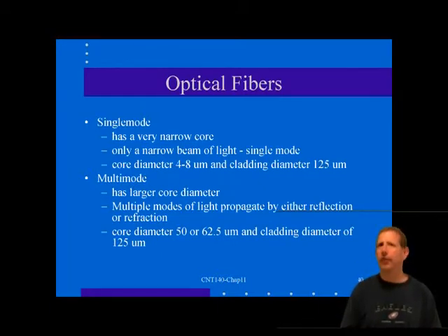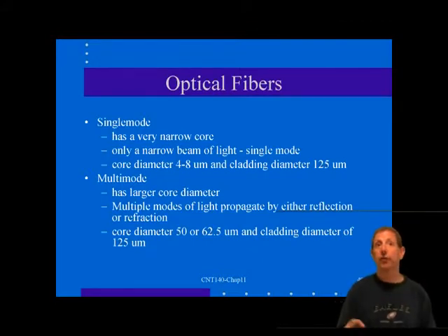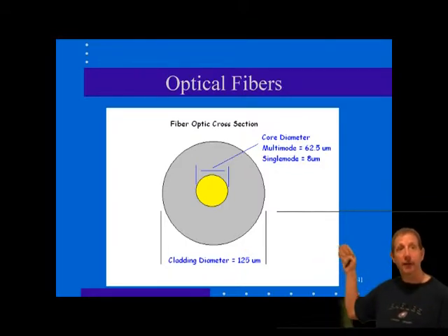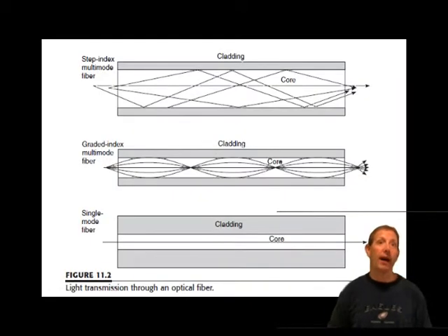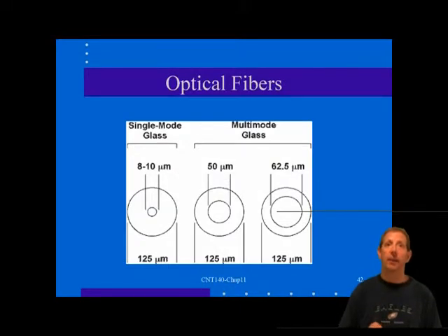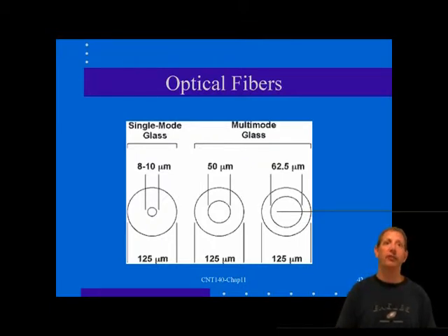Multi-mode fiber is further subdivided into two primary types, step index and graded index fiber. These terms refer to the gradation of the refractive index as measured radially from the center of the core. And as you can see behind me, the rays of light bounce off the walls formed by the radical step in refractive index between the core and the cladding of the step index. In contrast, in graded index multi-mode fiber, the rays primarily bend because of the gradual change in refractive index from the center of the core to the edge of the cladding.